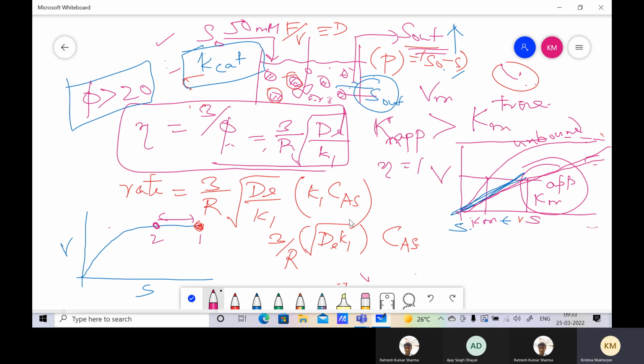Right? So this is reaction rate controlling when phi is very small. Phi is small. Remember this graph? But when I go here and it drops from here to here, notice that there is a tremendous drop in efficiency at first order. And phi is greater than 20 because your phi values are very large, because this is mass transfer control.